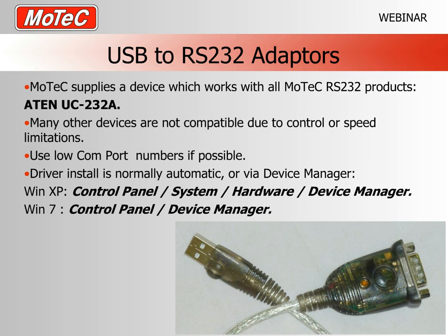The reason some other devices are not recommended is because some of our MoTeC devices use non-standard speeds, and a lot of the USB to RS232 adapters don't support non-standard speeds. So the reason we sell this one and recommend it is that it's been proven to work at every speed that we can throw at it, and it's a relatively cheap device. It's in the vicinity of, say, $20 to $30 Australian, and available everywhere. So if you need to use an adapter, I seriously suggest you either buy one from a MoTeC dealer or buy the same device from another supplier.